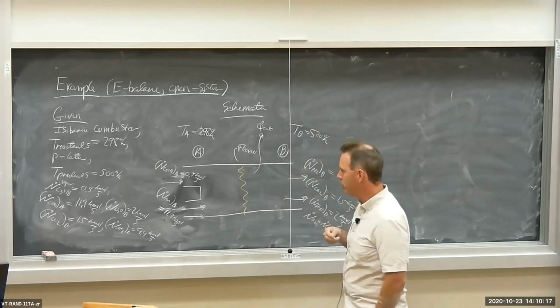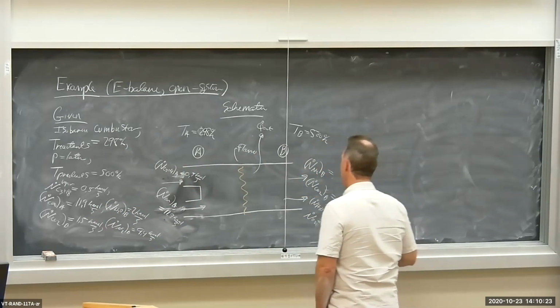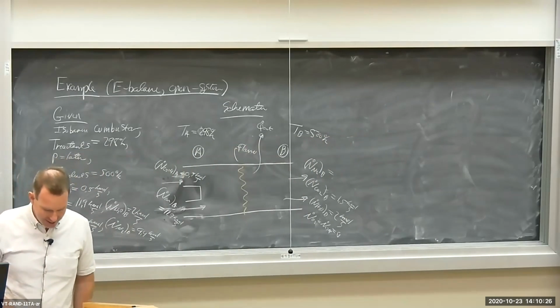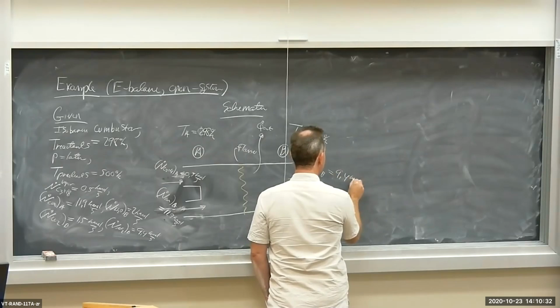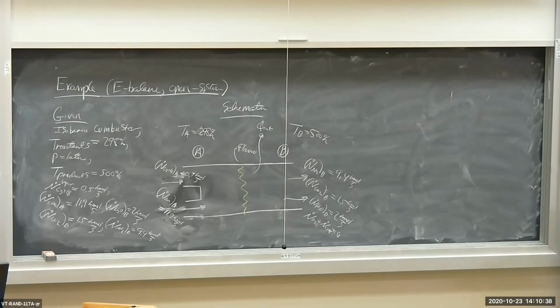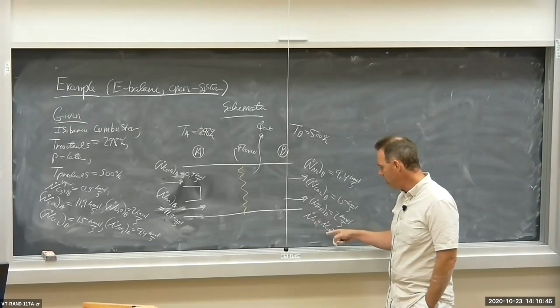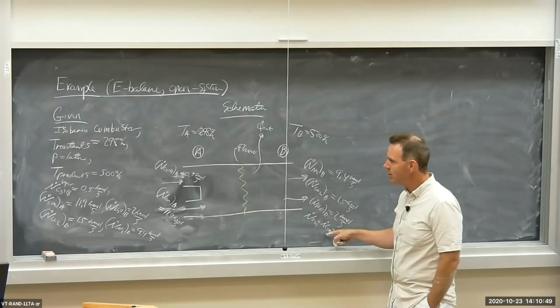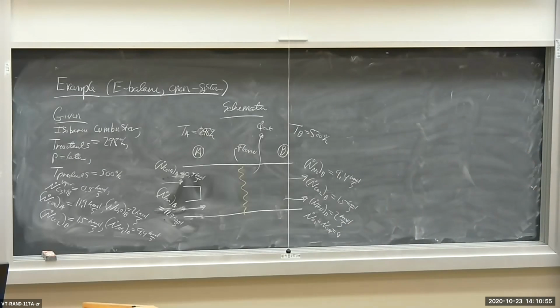The nitrogen is inert, so 79% of 11.9 kilomoles per second is 9.4 kilomoles per second flowing out on the product side. The remaining species, the O2 and the propane, have N dots of 0 because we have complete combustion. All the oxygen is used up and all the fuel is used up. That's the way this particular problem is set up.